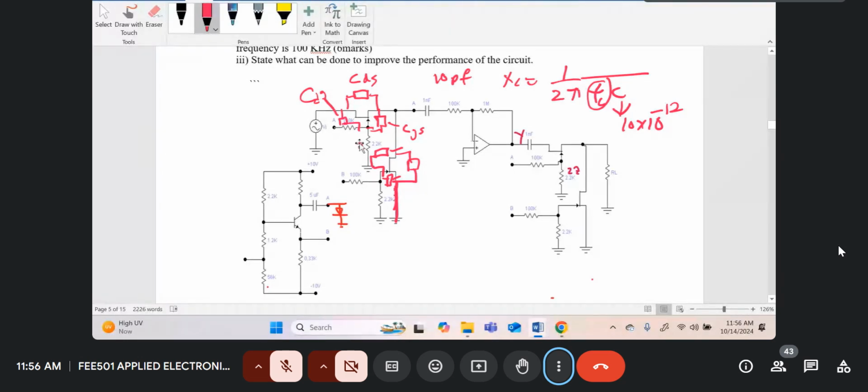So the problem will be, how do we get the total error? To get the total error, you go to get the maximum error. That's why I told you to do the exercise, put values, and we've calculated some theoretical values. So you can just substitute the values for RG, RL, RDS on, RDS off. Okay, so you get the on error, get the off error. Use the maximum, which is greater. Is it the on error or the off error? Use the maximum error you get.